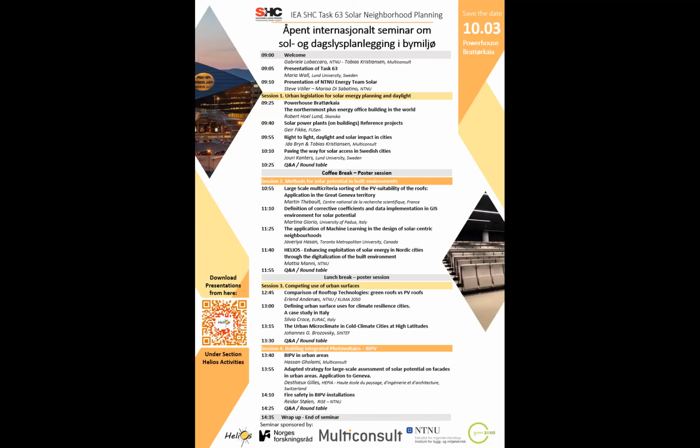I can say there are two main points. The first one is that the main application of BIPVT is to help ventilate the PV system to decrease the degradation rate and expand the lifetime of the BIPV system. But here in Norway, we don't need that much because it's a cold climate. That's one of the main advantages in Norway. Normally you have a longer lifetime for BIPV systems here compared to other parts of Europe, and also a lower degradation rate.